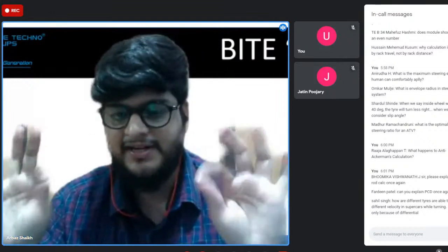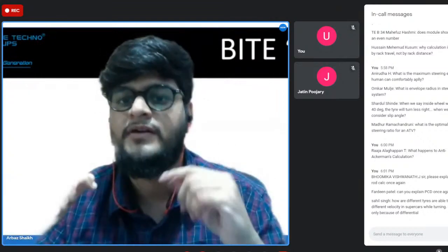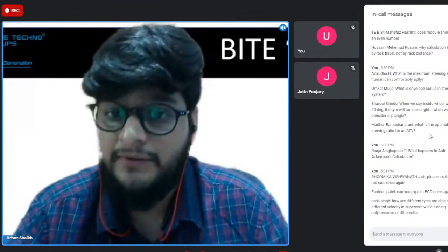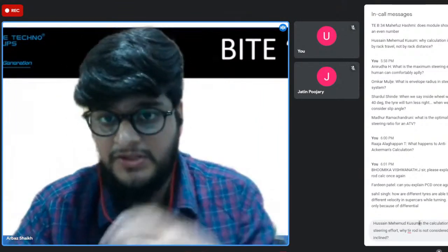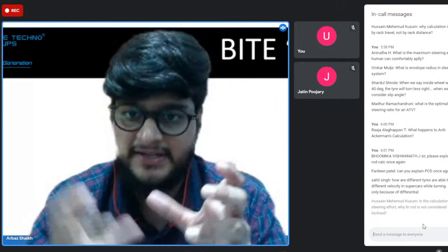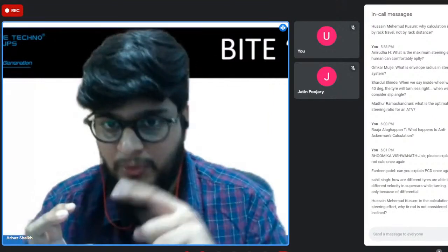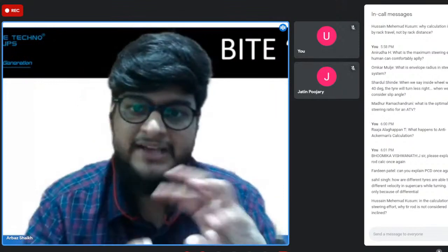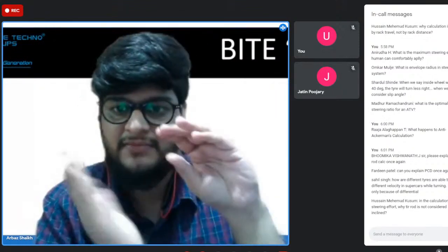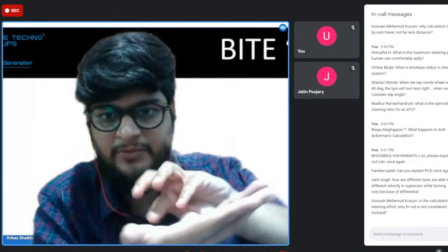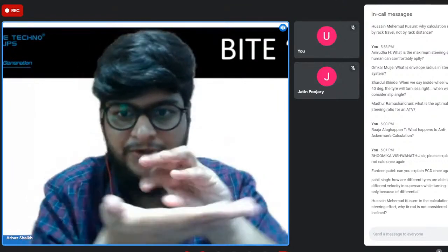If you turn it into a straight line, that line will have a length of pi d, the circumference of the circle, right? Now, whenever a pinion is rotated, the rack will be displaced by some amount. And if the pinion is rotated by one whole rotation, by 360 degrees, the rack will move by some distance, right? So imagine my hand to be this rack and my fingers to be the pinion. So if I'm rotating my pinion, my hand will move in the horizontal direction.